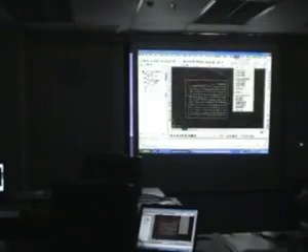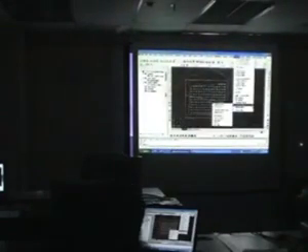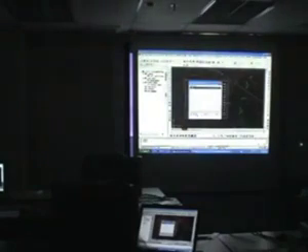For sections, if you need to generate any section drawings or section reports, you can click, say, plot all. I'm going to plot all the sections. I'm just going to put them somewhere here in the drawing. Because what it's doing now is it's generating all those different sections. That's why it's linking like mad.